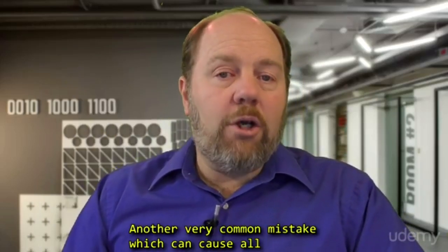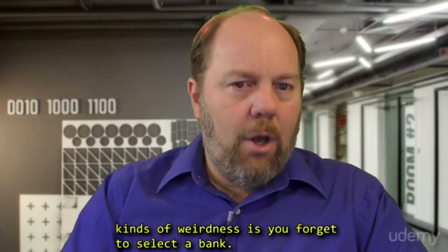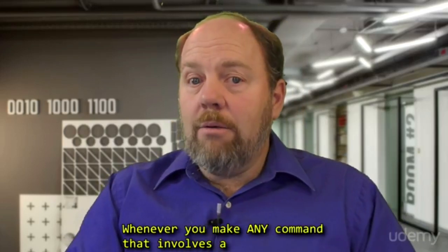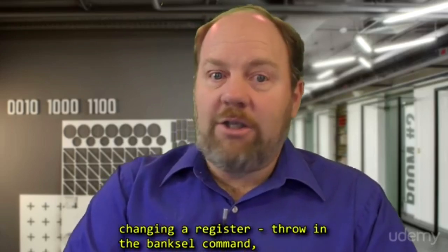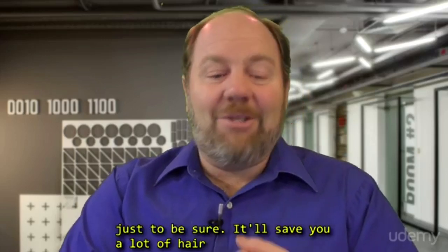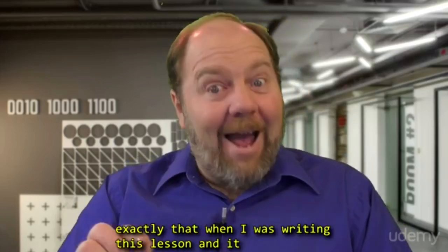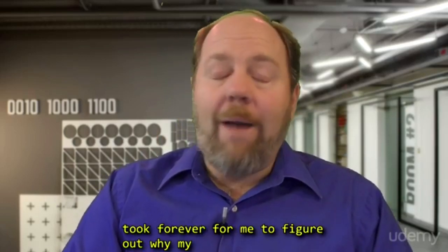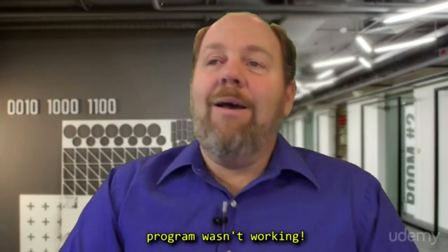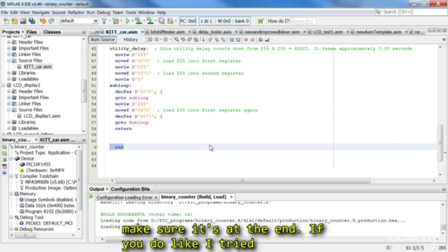Another common mistake which can cause all kinds of weirdness is you forget to select a bank. Whenever you make any command that involves changing a register, throw in the bank select command, just to be sure. It'll save you a lot of hair pulling and grief. Trust me on this one. I did exactly that when I was writing this lesson, and it took me forever to figure out why my program wasn't working. Your program needs to have an end command, but make sure it's at the end.